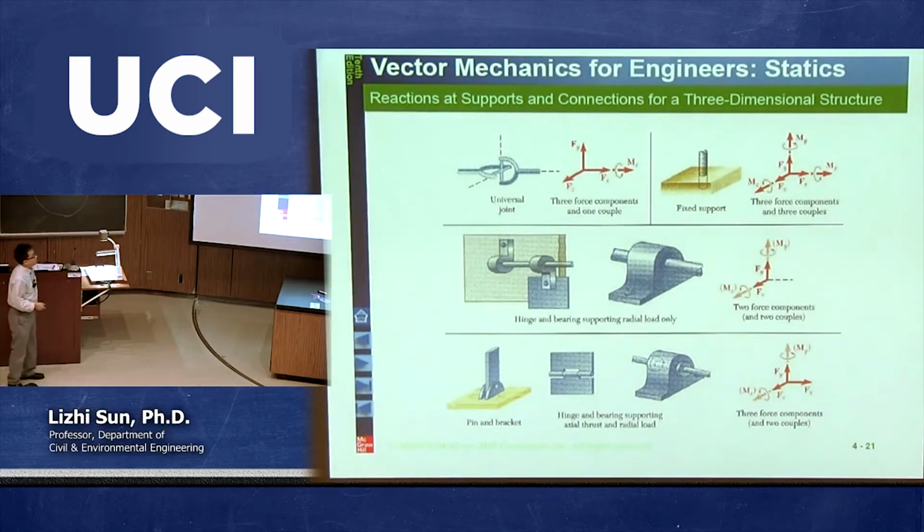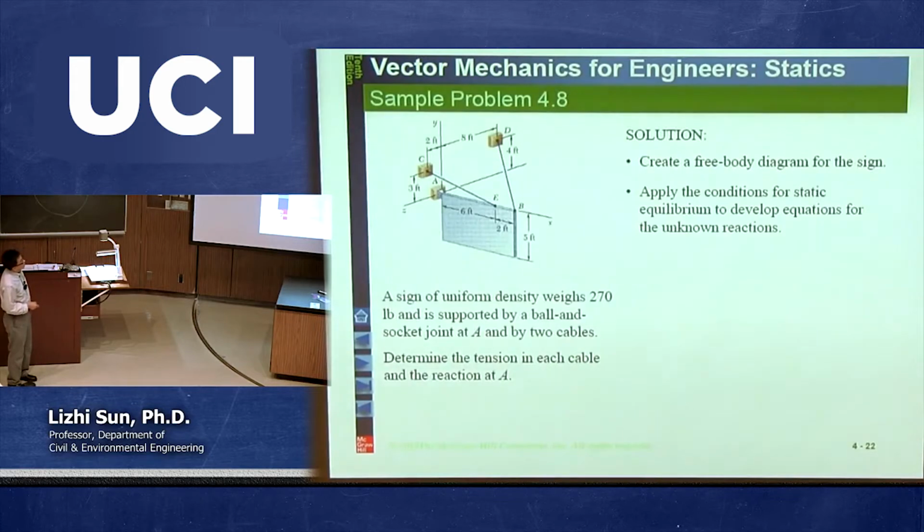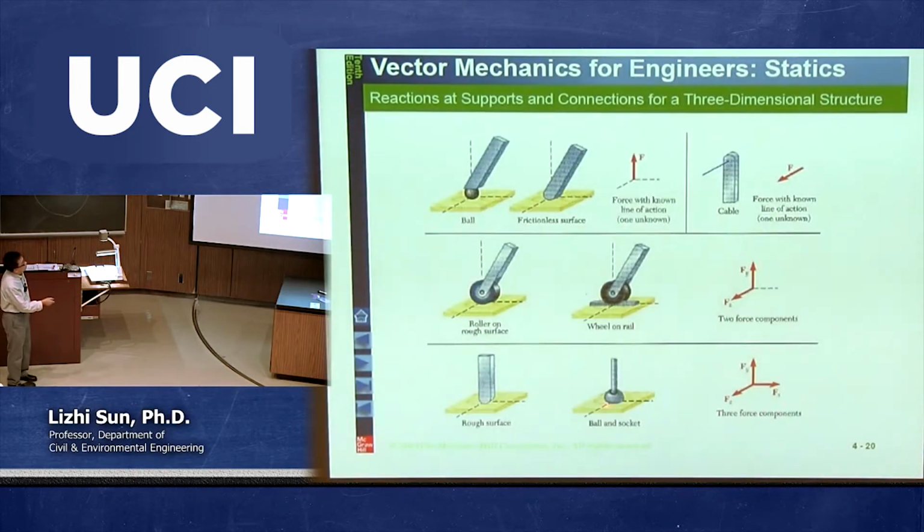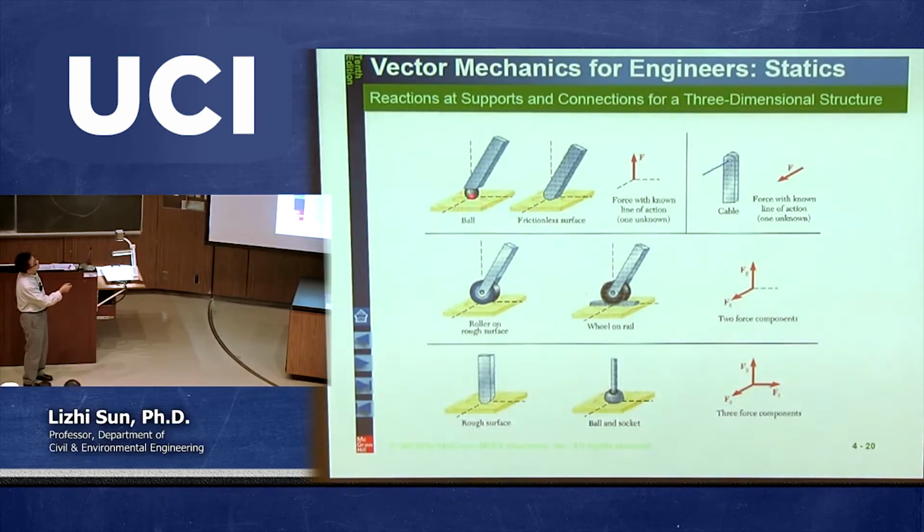Obviously, we have to recognize sometimes it's not easy to figure out what the corresponding reactions are in terms of forces or in terms of moment. The best way I can suggest is either you can see any scenario falling into one of these three categories, or sometimes you use your common sense to figure it out as well. Okay, most of the time we have either a fixed end or what we call the ball and socket support. And sometimes we have this kind of ball support.